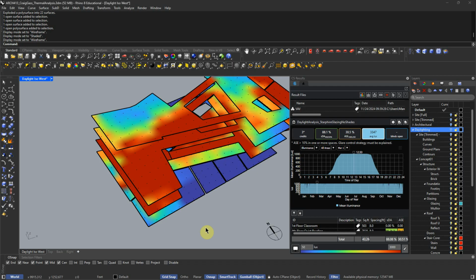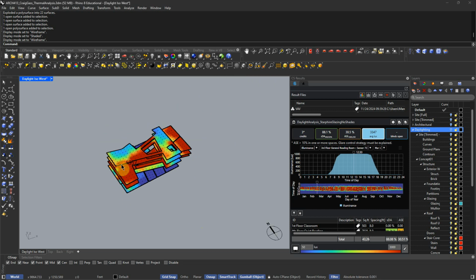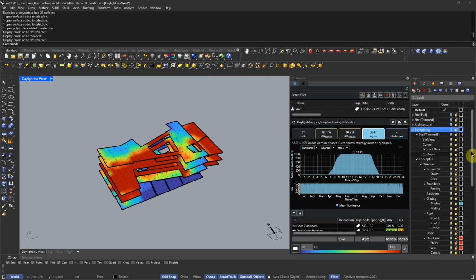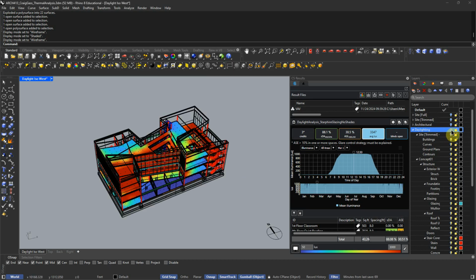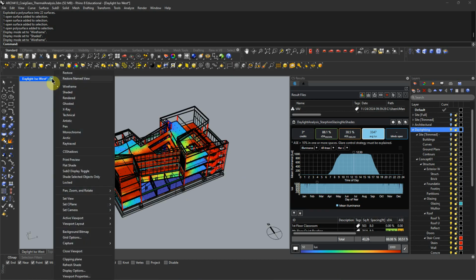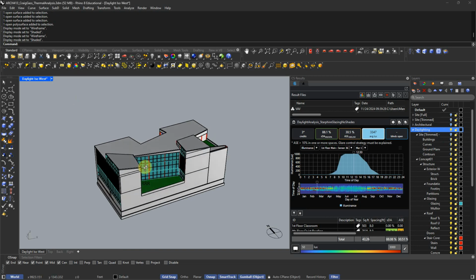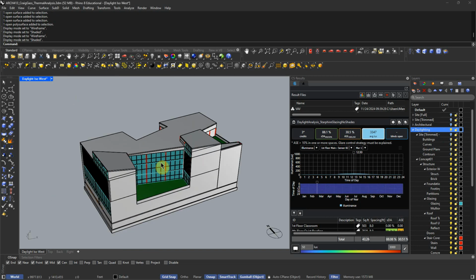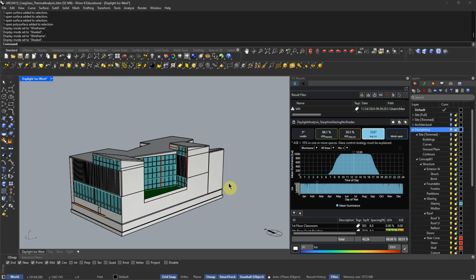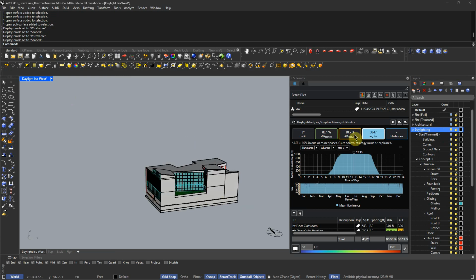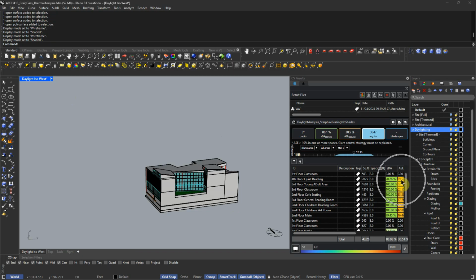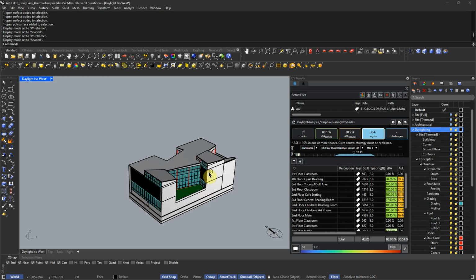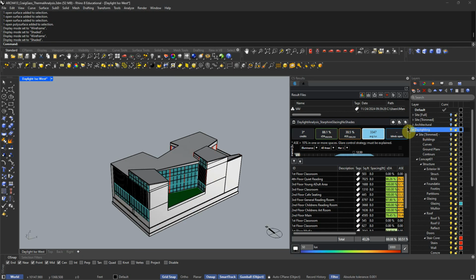It's 2 hours a day. That's always going to be there. It blocks that sun, and that fixes the problem because the rest of the day it's fine. So that's where a glare study comes in. So if you do those adjustments to your floor plates or your work surfaces, then you'll be able to iterate in the ways I was just describing, trying to get this ASE to less than 10% for all these spaces. All right, so let's look at your thermal analysis.